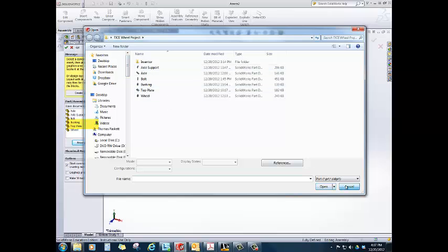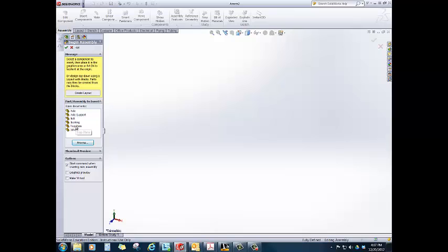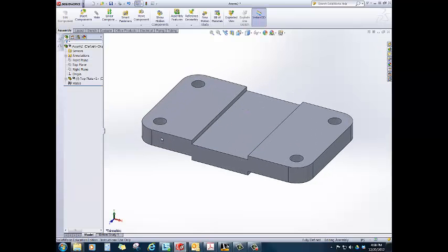I'm going to again start by selecting the top plate, which is part 1 of our assembly, and once I highlight it here on the left, I simply select the inside of my drawing editor or my screen and place that drawing into view. That would be step 1.